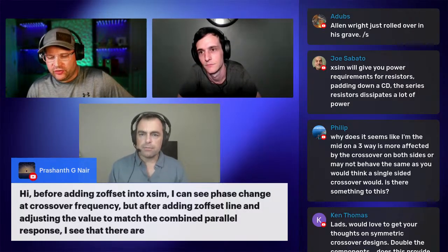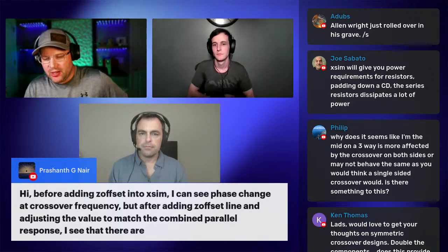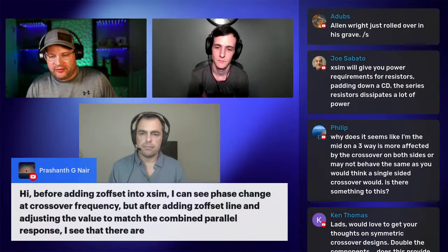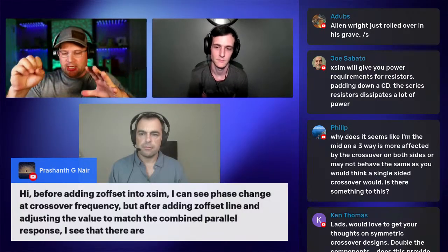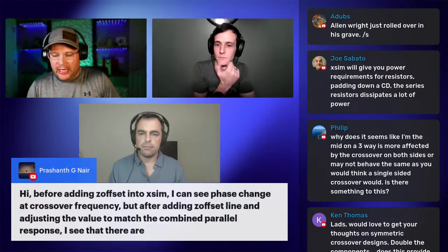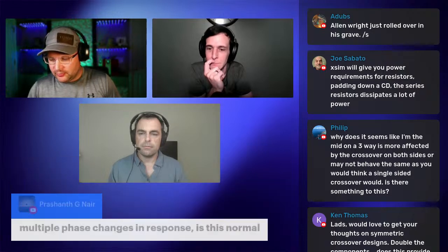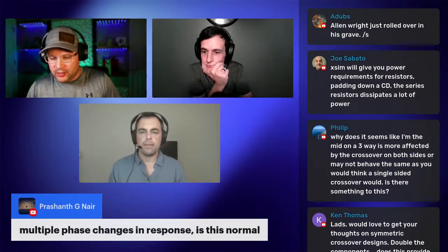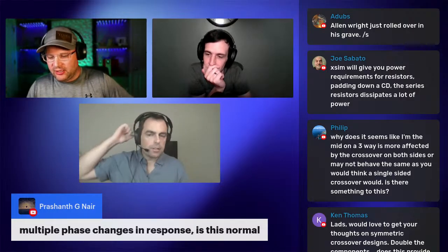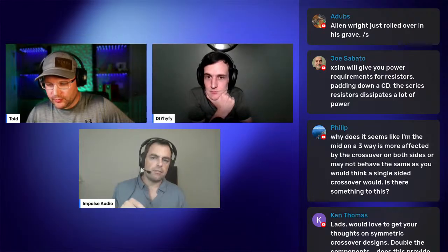I'm not sure. I don't know what he's saying here, so I'm wondering if you guys understand what he's saying. Before adding a Z offset in XSIM, so he's got his two drivers in XSIM, a tweeter and a woofer. I can see the phase change at the crossover frequency, but after adding the Z offset line and adjusting the value to match the combined parallel response, I see that there are multiple phase changes in the response. Is that normal? Okay, so when you change your Z offset in the software, your phase is going to move.